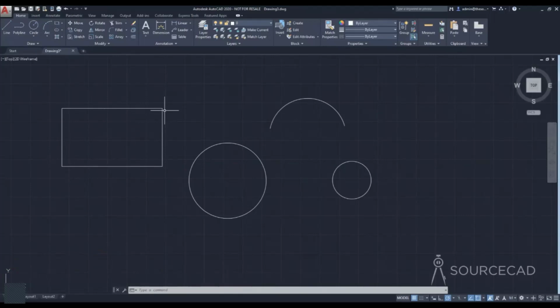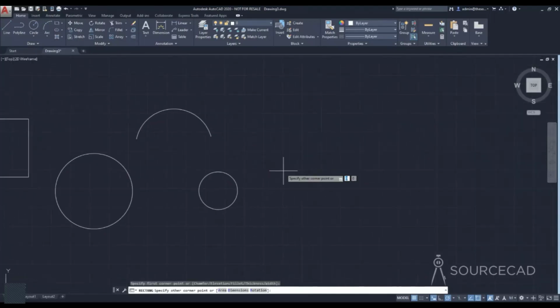If you want to make it precise, then you can specify the length and breadth. Activate dynamic input by pressing F12 and go to rectangle, so that we have this tooltip now. So you can now click at a point, create a point.